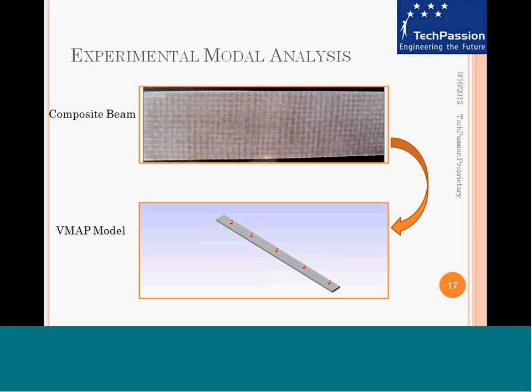One of the things that I want to point out here is it's very difficult to incorporate damping in a simulation model. So that is where performing modal analysis through experimental methods comes in. And there are a lot of myths the moment you think of structures made of composites. People have a lot of questions about, okay, this could be really damped. Now, is it possible to measure damping also? What kind of experimental setup do I need? Is it going to be single input, single output, multi-input, multi-output? All of those questions could arise.